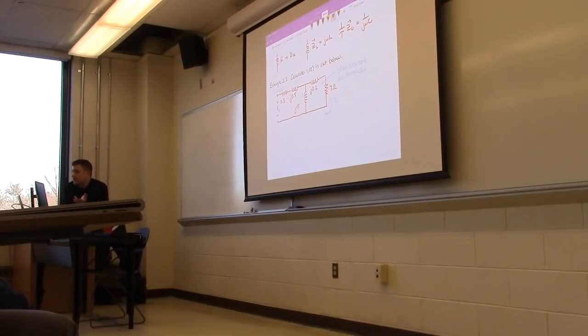Now we're using phasors, but all the other methods you learned are exactly the same. For these early problems, imagine it's a DC circuit and how you would have treated it before. Like you said, combine the two branch impedances that are in parallel, then combine in series to get a single equivalent impedance for the entire network, and then divide.